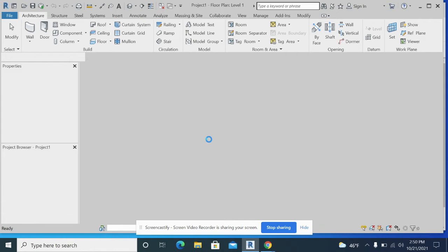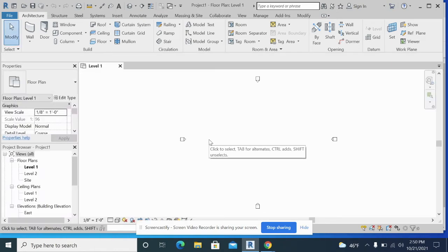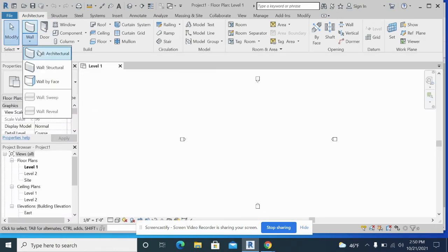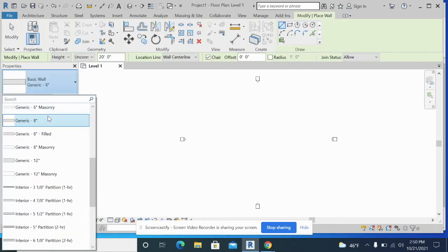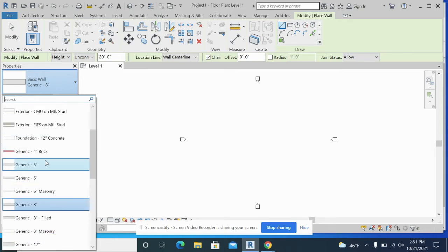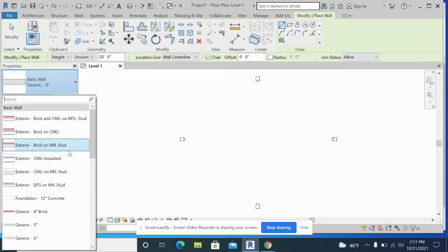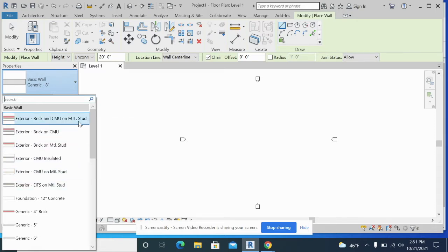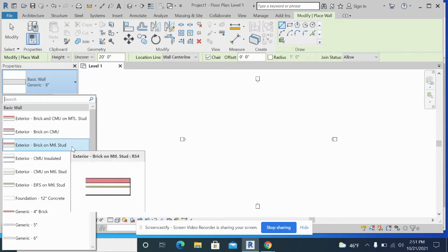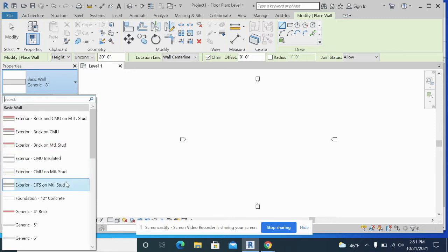We're also going to create a new type of exterior wall, because when we look at our different walls in here, there's like basic wall, which is really just solid concrete. But for exterior, a lot of these are really commercial types of exterior walls with metal studs. Metal studs aren't very common in residential homes. So we're going to change one of these to become more common to what you'd find on the outside of a house, kind of like what we did with our shed.